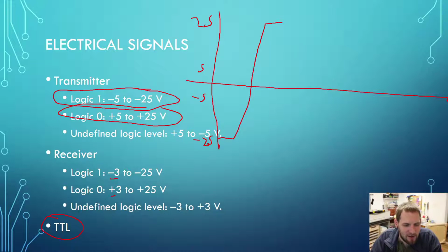So actually with TTL, we're not doing -5 volts. All we are doing is 0 to 5 volts. If we want to use a TTL transmitter, like our Arduino over here, which is serial, which is still what RS232 is, with something that is meant for straight up RS232, we have to use what's called a line driver, and that is going to be the intermediary. It takes that 5 or 0 volt signal from the Arduino and converts it into acceptable voltages.